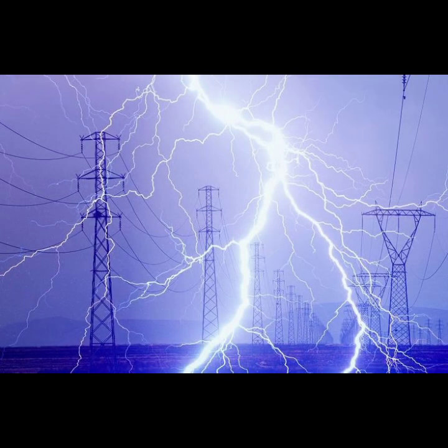Number 3. Wide range of frequency. Lightning discharge does not have a fixed frequency like AC does. Instead, it contains a wide range of frequencies, due to its rapid acceleration of charged particles and transient nature. This frequency spectrum can range from a few kilohertz to several gigahertz. On the other hand, AC typically operates at a single and fixed frequency of 50 or 60 Hz. This makes lightning discharge not to be considered as AC.